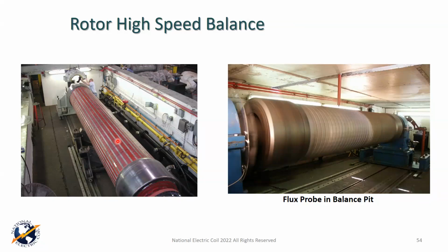Overspeed from a maintenance standpoint is 10% over, or 110%, okay? When machines are typically manufactured brand new, they traditionally go to 20% over, okay? Now, there are people saying, well, Jesus, if that's good for brand new, we ought to require it for rebuilt. It doesn't work that way, because you're not considering the stresses that are put on the forgings and on many of the components.